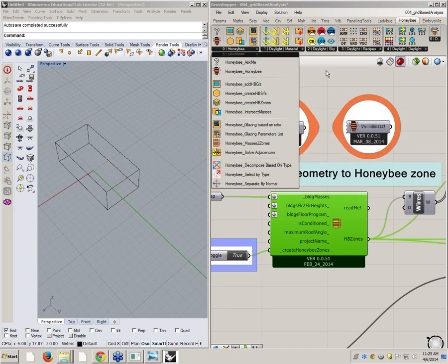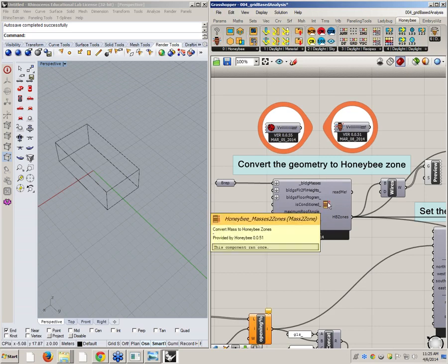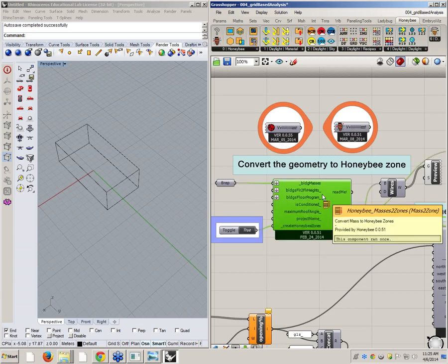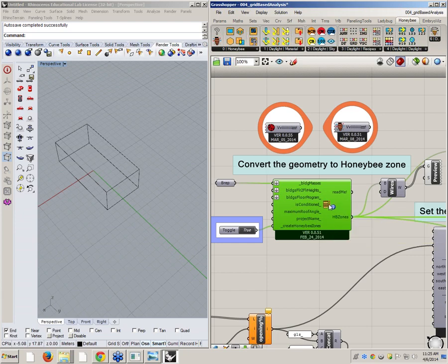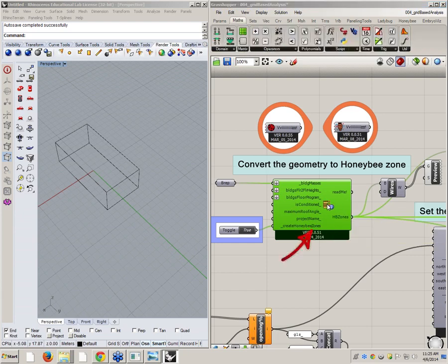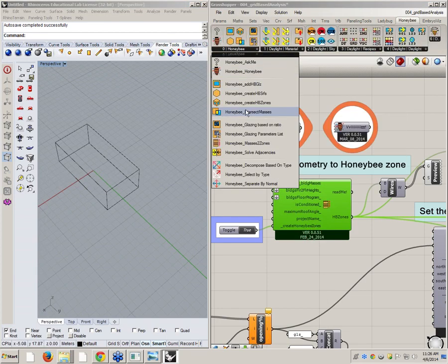Down here. There is an issue because these things are user objects. They're not the real Grasshopper GHA components. If you do the trick that I showed you last time, it will show you a Python component, because this is really a Python component. It's just a Python component with all the code. So this trick won't work for Honeybee and Ladybug. So this is here.